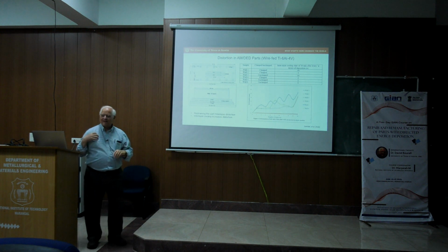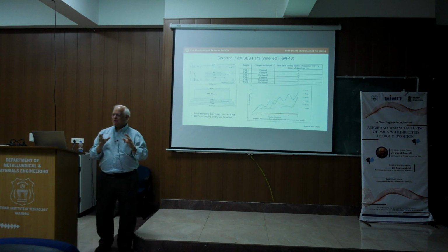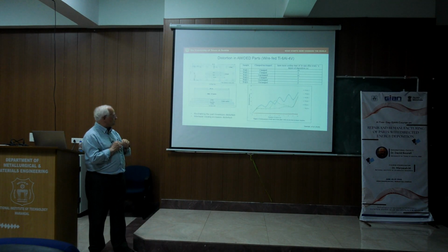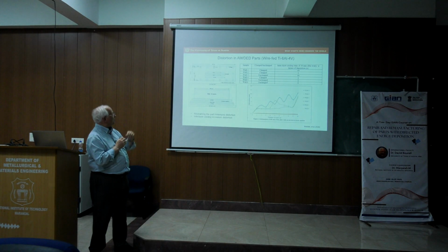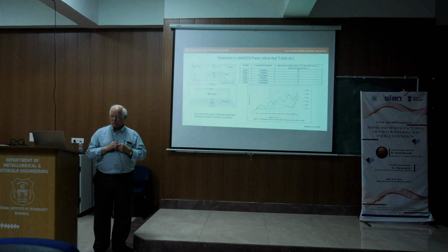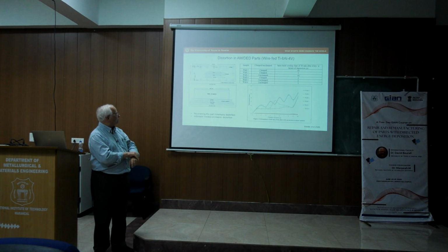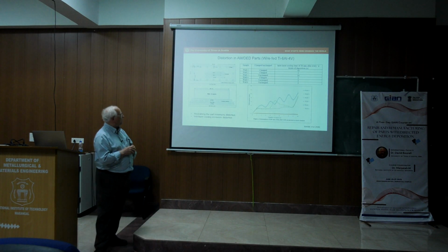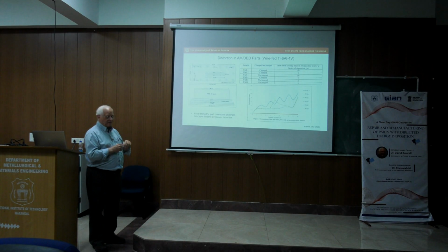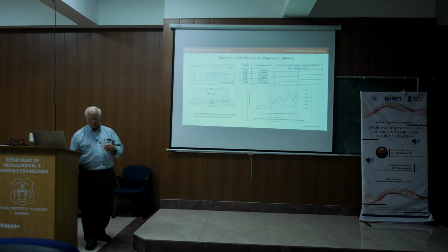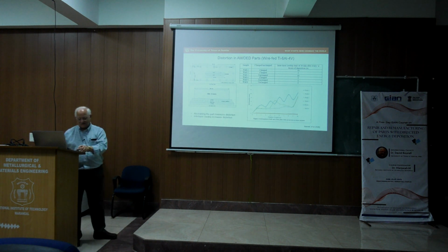It turns out that there's an alternate approach to using support structures, and that was demonstrated by a researcher working with DED, again wire-fed titanium. What they did is they used a brute force approach where they just clamped down the build plate in a way that restricted it from moving during the build. So you can see